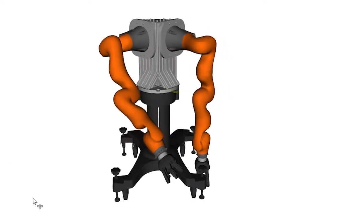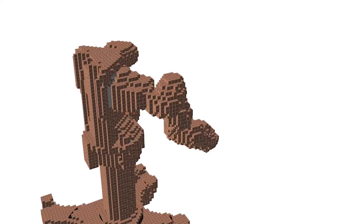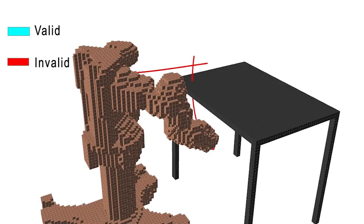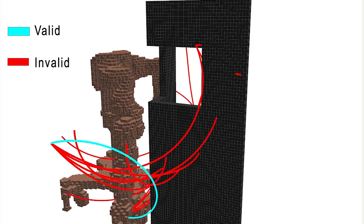We apply selective densification to a 7-jointed robot arm. Here, a node in the graph represents a 7-dimensional configuration. We check collisions by voxelizing the robot and obstacles. Here we show all the edges checked during a search. After smoothing, we find a short path to the goal. Finally, we show selective densification planning into a tight space.